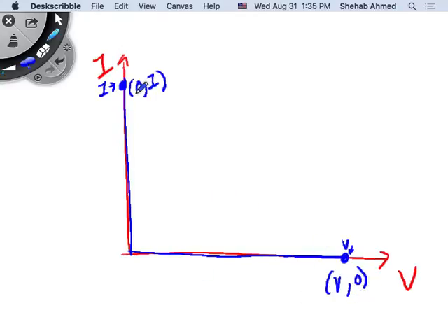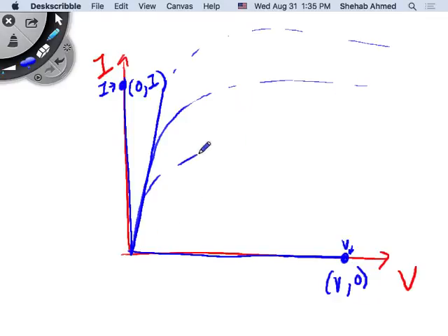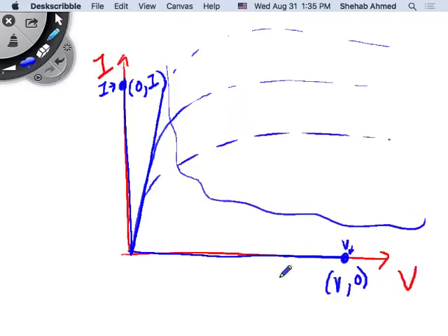But this is ideal, I'm not really doing that. In reality, what's actually happening is this line is actually a little bit to the right. This is the reality. These are the characteristic curves of the MOSFETs or BJTs or whatever device we will talk about today. Right? These are the curves. I don't care about this part of the curves. I will not use it that way. I will only use it along this straight line and this line. Which means, fine, I have some power loss.